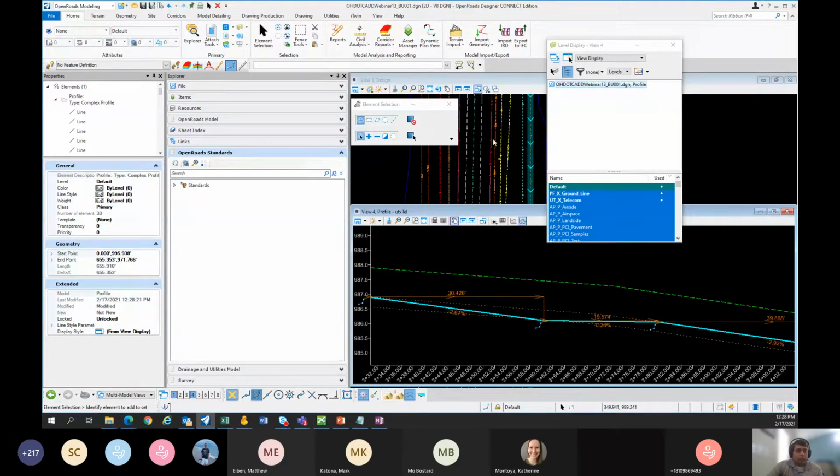It's not there yet. Another thing to watch out for is the direction of this line. The way the extraction works depends on how the line's drawn, what direction this utility is going in. Right now the arrows are going down, but there very well could be a case where when you extract it these arrows are going up.